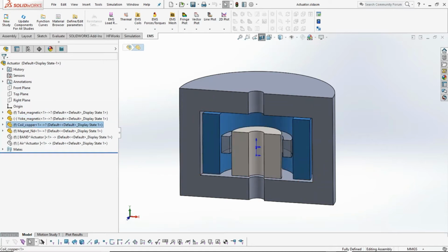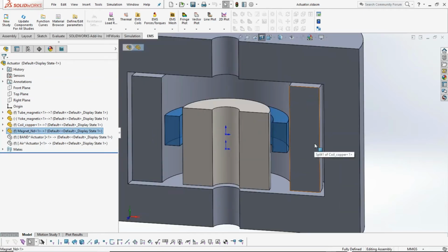This is a wound coil, and it is important because only when you energize the coil will the actuator actuate from one position to another. Once you stop the current in the coil, the actuator locks onto the position that it reaches. Then finally, there is a radial magnet that forms a very important part of this actuator design and completes the magnetic circuit.